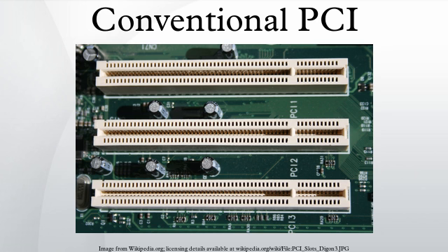Cache snooping. PCI originally included optional support for write-back cache coherence. This required support by memory targets, which would listen to two pins from the cache on the bus, SDONE and SBO. Because this was rarely implemented in practice, it was deleted from revision 2.2 of the PCI specification, and the pins reused for SMBUS access in revision 2.3.